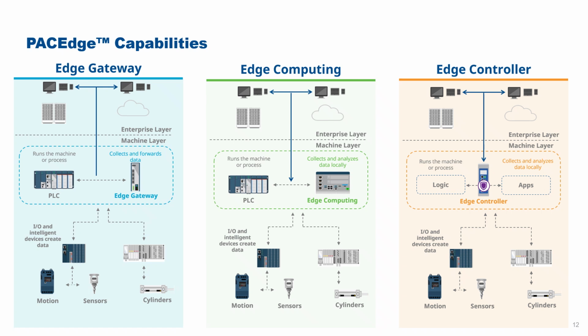It needs to be close to the PLC because we want to make sure that we're operating within time, and there might be an awful lot of data there. So sending that up into the cloud and then having it processed in the cloud and sending it back, yeah, you might have a very long latency there. So with the edge computer, we can reduce that latency, and we can also reduce the amount of data that needs to be sent and performed and collected across the different layers.